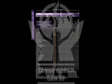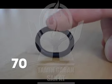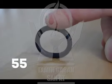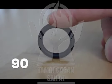for your application. The same material is often available in a range of different hardnesses. The hardness is typically expressed as the durometer hardness. 70 is a fairly typical hardness and is good for most uses. 55 durometer is much softer and is a good choice for pressures below maybe 1,000 psi because it is easier to install and less sensitive to surface finish.